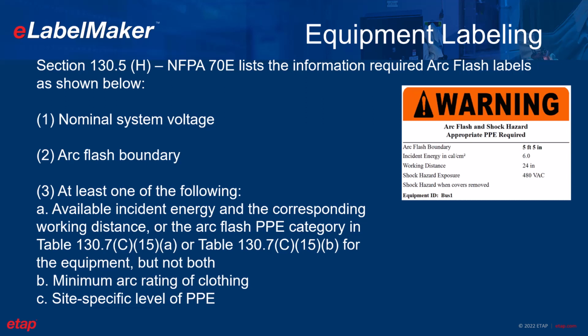However, this section clearly explains that there are several possibilities and combinations of different parameters that could go into an arc flash label. And on top of that, when you are using the arc flash incident energy analysis method, several pieces of equipment can experience different incident energy values.